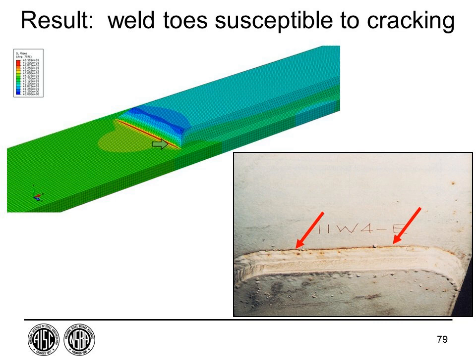Well, I see high stresses from live load because the stress, like water, has to come out and get into the base plate. And remember, I have high locked-in residual stresses here. The result, cracking at the termination. That's what we're looking for when we go out and inspect.